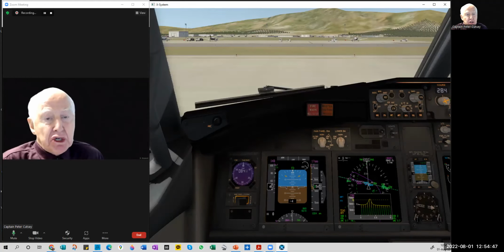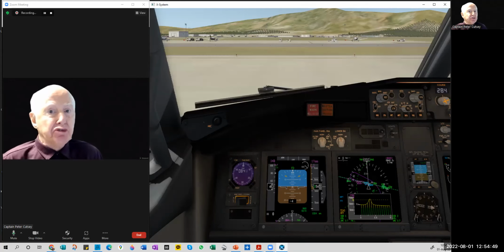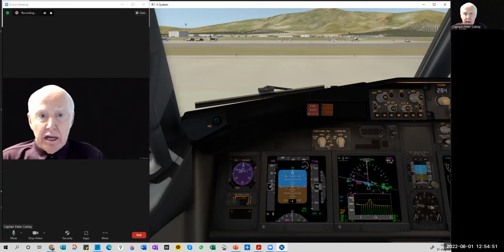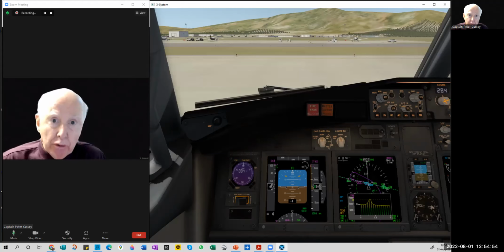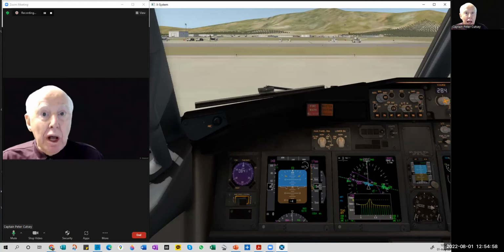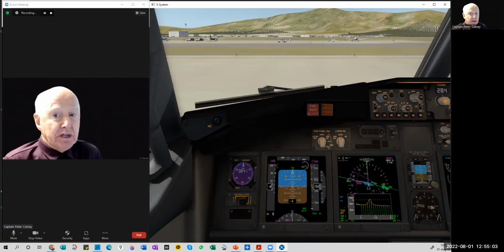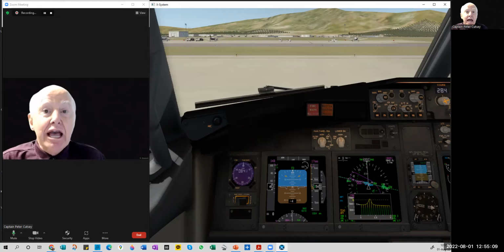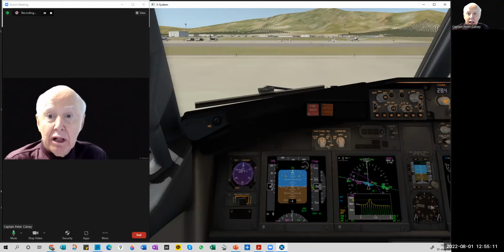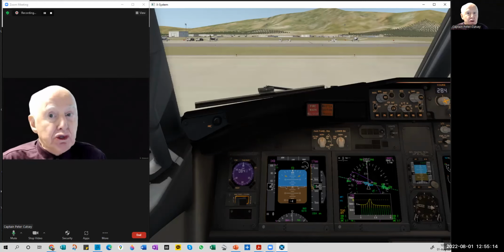There are ways in which we can actually increase the efficiency of our aircraft, that is, more power for a certain situation by doing a no engine bleed takeoff. So there are procedures in the FCOM, in the supplementary procedures, and that's what we're going to cover today. And I'm using Kabul as an example because it is a high altitude airport and terrain is a consideration.